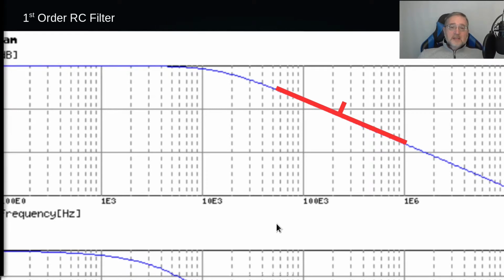But unfortunately I dismissed entirely this problem in the previous episode, and so I ended up taking the measurement in an area of the diagram where the slope was changing and at that point was only 10 dB per decade. In reality, I should have taken the measurement at a higher frequency to avoid the error caused by the changing shape of the diagram. The correct measurement should have been in the 20 dB per decade range, as the theory suggests. Because of that, I went back to the lab and repeated the measurements in the right way, and I am now showing how I did it. After that, we will start talking about today's topic.